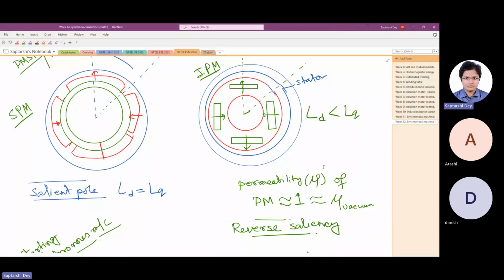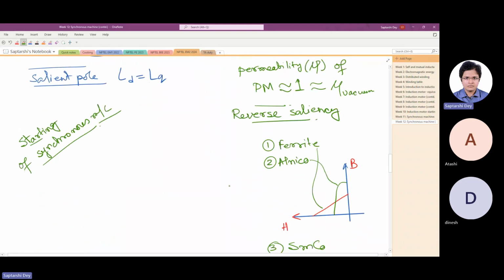Let me recall what my colleagues talk about. Winding wise, like improving winding factors, but those are classic. Then control, then this kind of thing, say for example the two torques that I talked about: magnet torque looks like this, and reluctance torque looks like this. So the summation is somewhere here, and optimizing that ratio so as to get the maximum power out of it is this kind of work. Then the EV boom came.